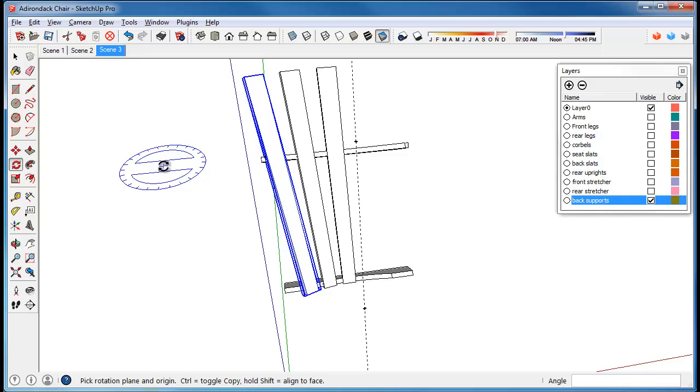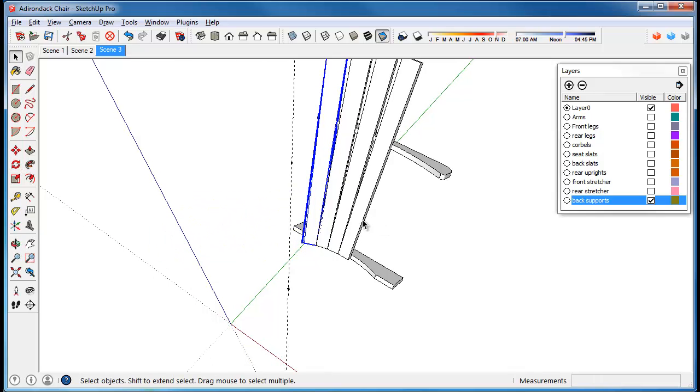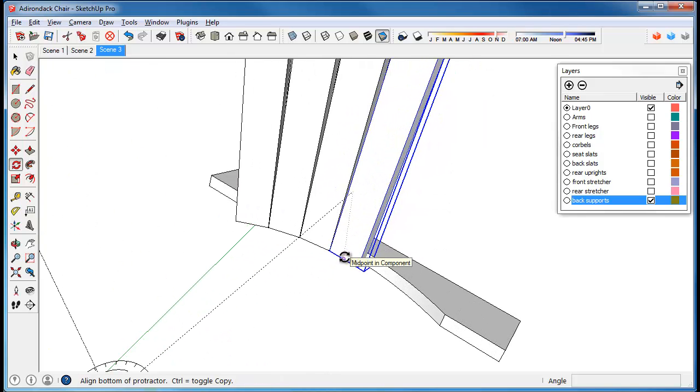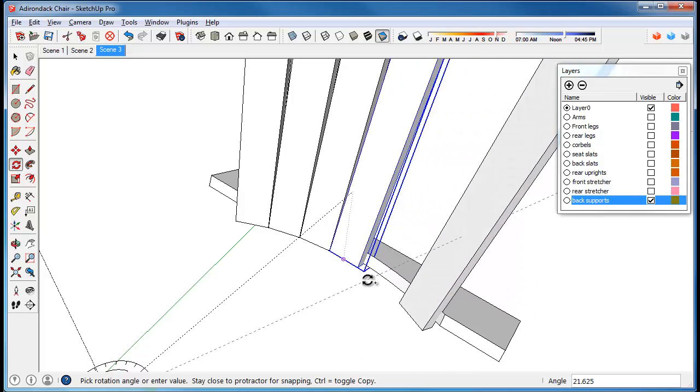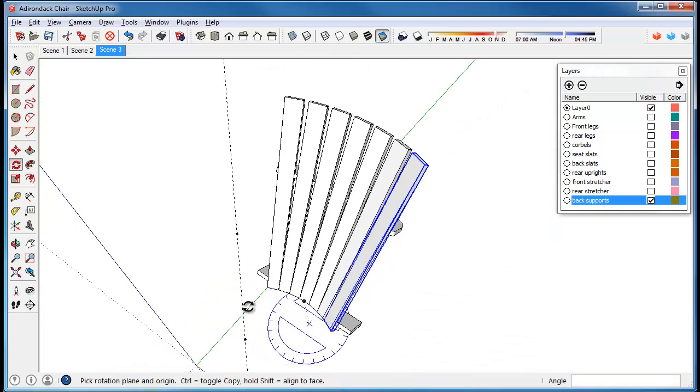That's probably a little wider spacing than I want here, so I'm going to change that to 3 additional copies, not including the center one. And we're done with that. Now, let's select that middle one, and we'll repeat this process. So again, click and drag, click on the midpoint. Actually, it doesn't even matter if you grab the midpoint, it's just easy that way. And whoops, I hit the control key just now, and we'll type 25 and hit enter, /3,